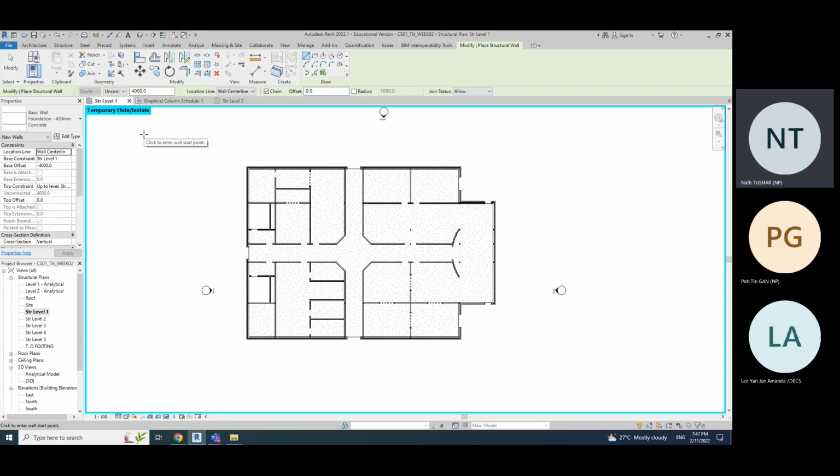Now, don't click on anything first. Let me ask you a few questions. In case your base offset is showing a value, make sure that you are giving it a value of 0. Base offset should be 0, and press tab. If it's 0, it's okay. If there is any other value on your base offset over here, make it 0. Okay, got it? Just make it 0 first. Later on, we will explore what that offset means.